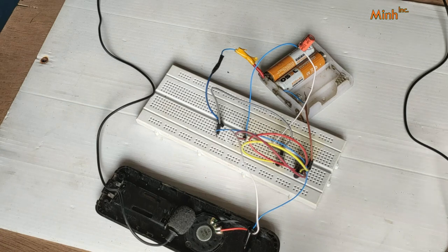Okay, so it is clear that everywhere it is the same. With the 10 microfarad capacitor, two sounds were quicker and then the third was very long, then again quicker, then the third. So charging and discharging happen through different resistances, and that is the time gap we are seeing.